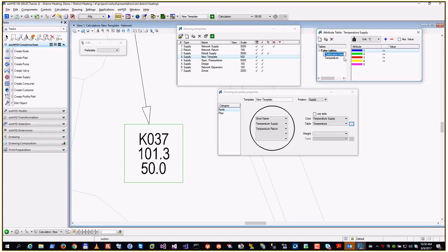Give it a new name. Supply temperature. By default, it starts with 5 intervals. You are free to remove or add new rows into the table. What you need to do is to enter values on the right side to complete the table.